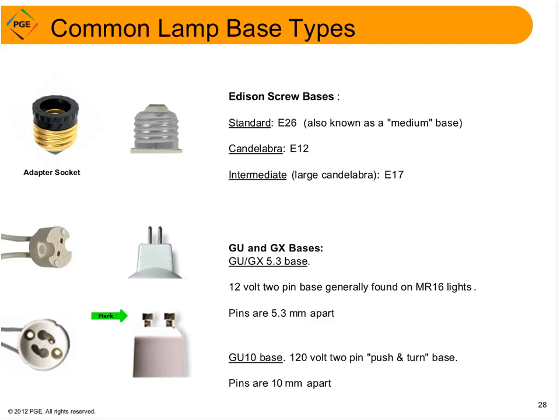So this illustrates again that you need to know what kind of lamp you are replacing so that you can get the correct LED replacement. It's not that hard, you just have to do your homework and pay attention. So in summary in this section, LED directional replacement lamps as well as LED downlights are examples of upgrade options that make sense right now and also qualify for some great cash incentives.